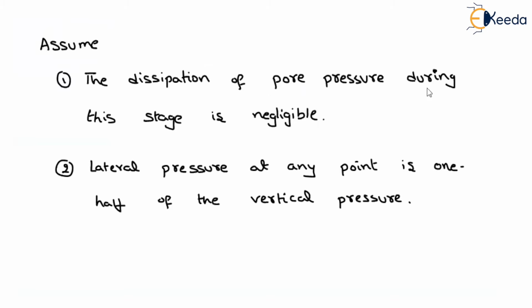The dissipation of pore pressure. What are the assumptions we have to consider? The dissipation of pore pressure during this stage is negligible. So we should not consider any dissipation of the pore water pressure. That means water is not expelling. And what is the second condition? Lateral pressure at any point is half of the vertical pressure.